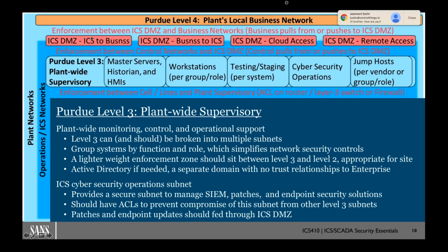I would not, and I repeat, I would not let your enterprise SOC, or a third party for that matter, reach back through the demilitarized zone into your cybersecurity operations inside of the control network. I would not let that occur at all. If they find a compromise or an incident they feel is valid, they hand that back to the cybersecurity individuals who deal with operations inside of the SOC. Have your dedicated small team do the actual cybersecurity operations in the control network, and only send the outside world a subset of the events, just enough to do level 1 reporting.